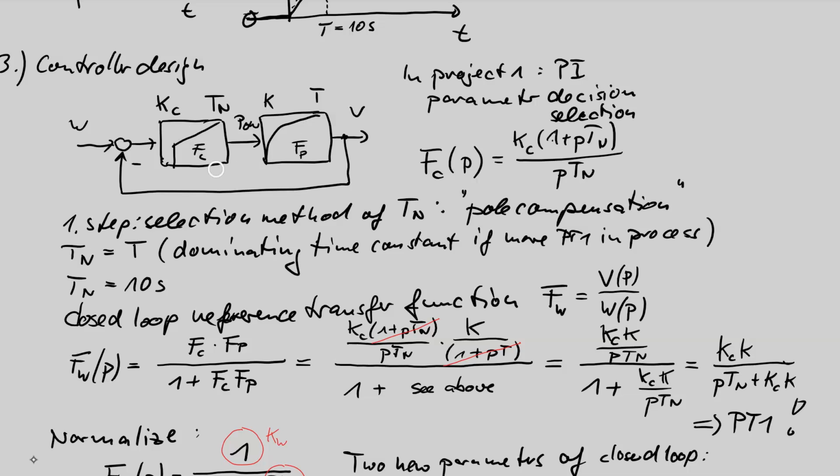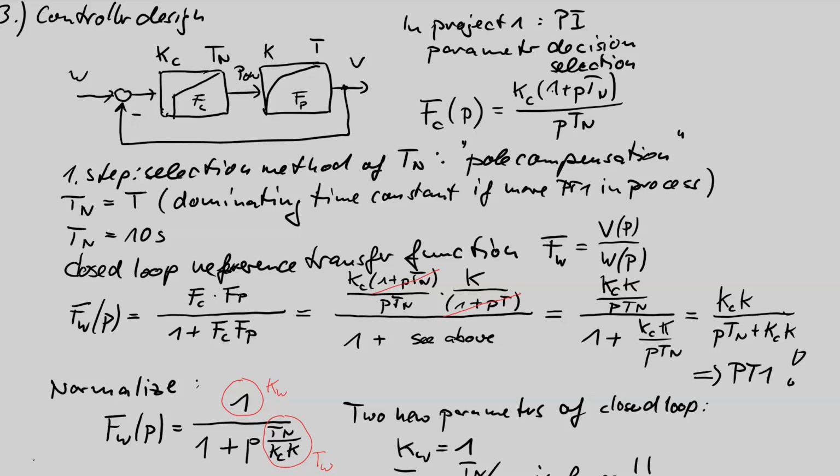So first, I just want to type in this signal block diagram. K then is 2.5. We have identified this. T is 10 seconds. We set this to 10 seconds, and I want to start the simulation with a KC of 4. The power unit is kilowatt. The time unit is seconds.